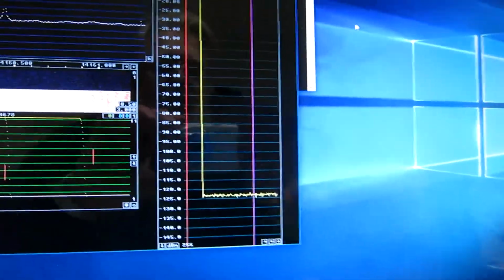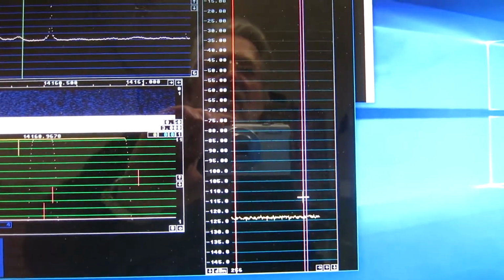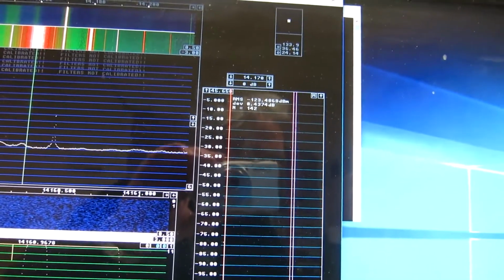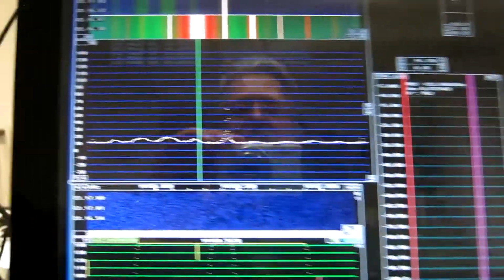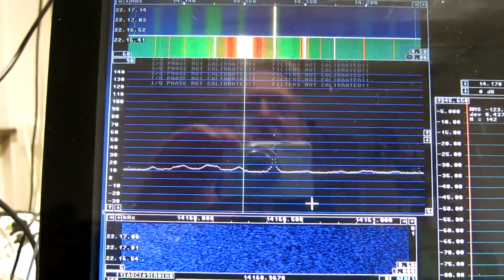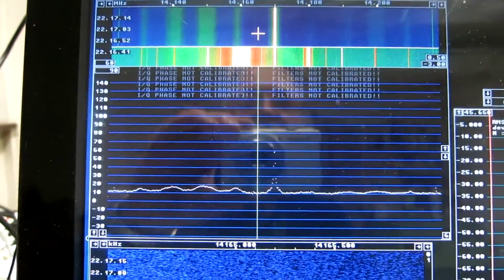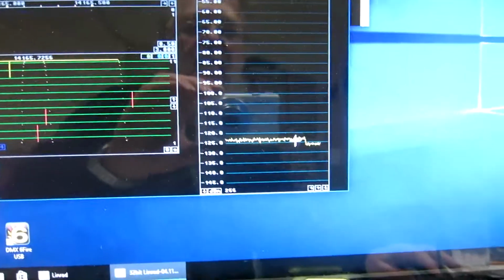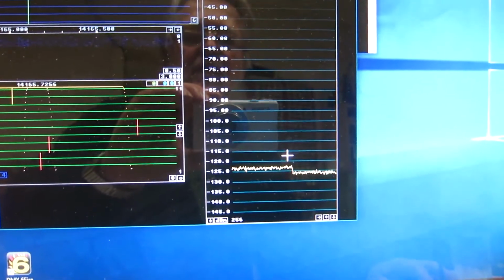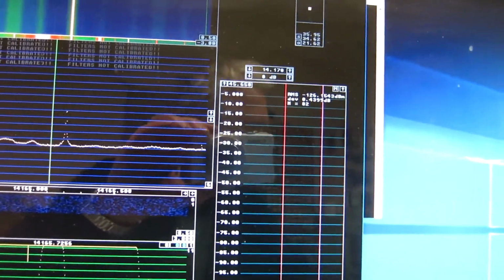As it happens, I'm not on a minimum and also not on a maximum. And at this point, the noise floor is minus 123.4. If you have this card and want to use it, you would listen for weak signals close to the center. I would click here, for example, and there the noise floor is quite good. Something like minus 126.1.